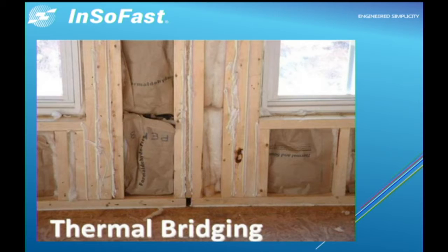You know, fiberglass insulation, when installed correctly as an R-19 batt in a 6-inch cavity, will achieve that R-19, but the wood studs on either side are only going to be an R-5, 5.5. And 20% of the wall is going to be R-5 and R-5.5.